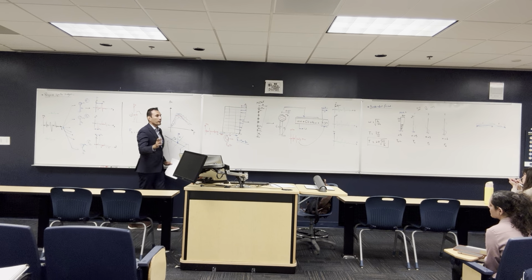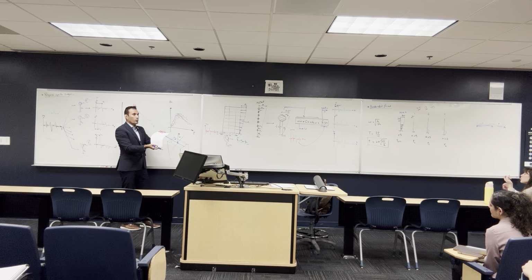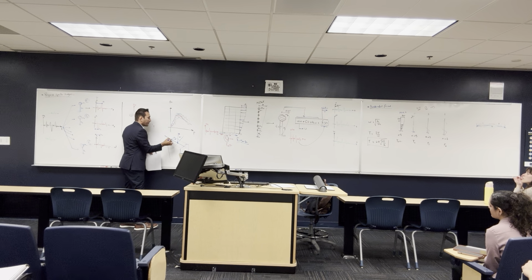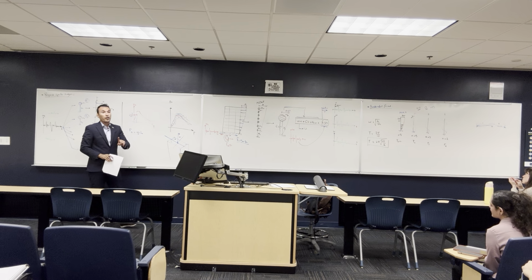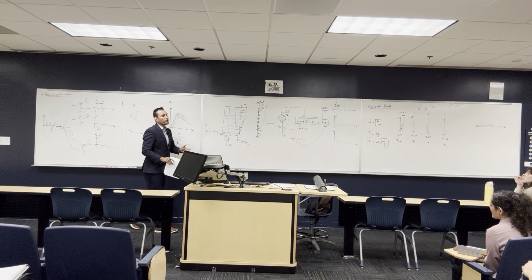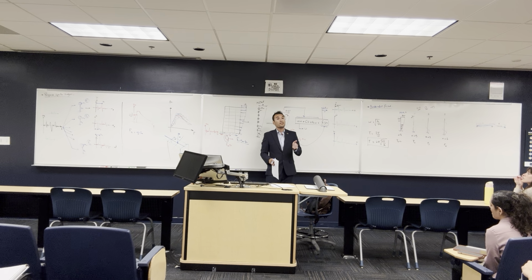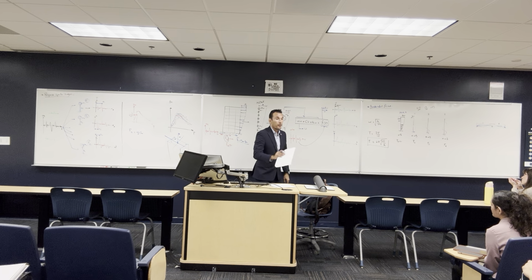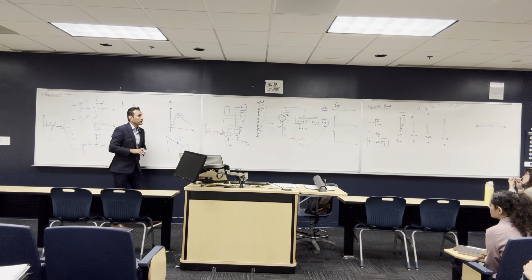And we always design for positive and negative moment. The earthquake might be this way, but it might actually make another moment the other way. So the reinforcement that you have here, you put something similar on the other side. That's why you find it all the way around. And even if the column is having just a pure axial force, sometimes we put reinforcement so that both the concrete and the steel can take the load. We distribute the load between the steel and the concrete.